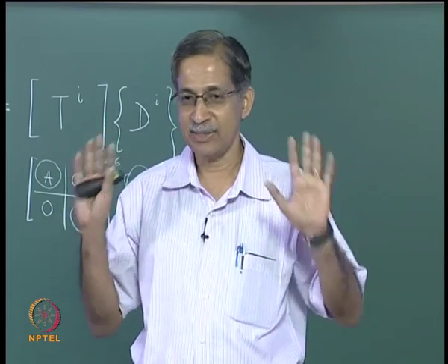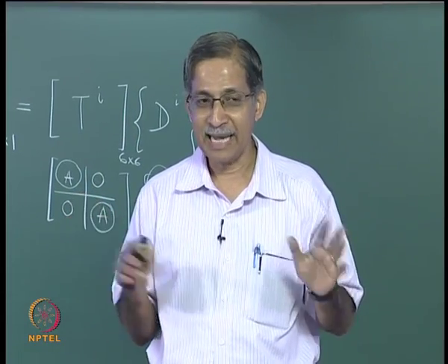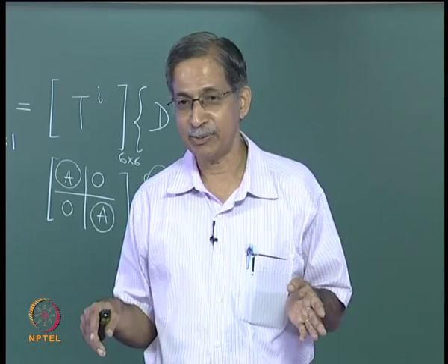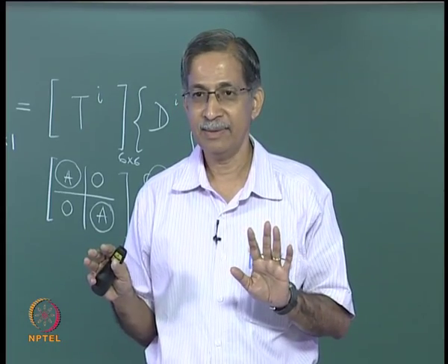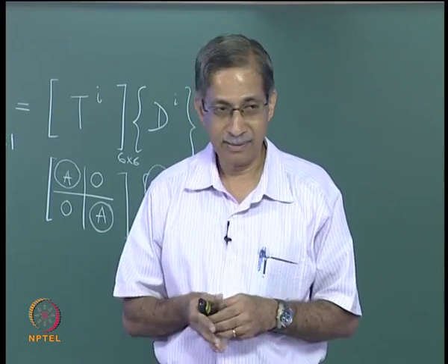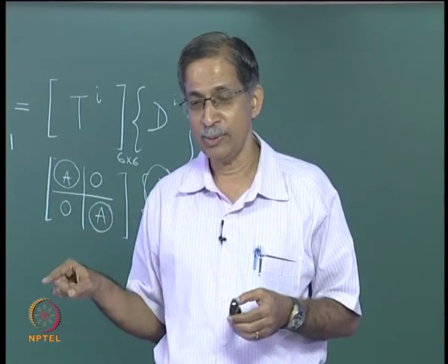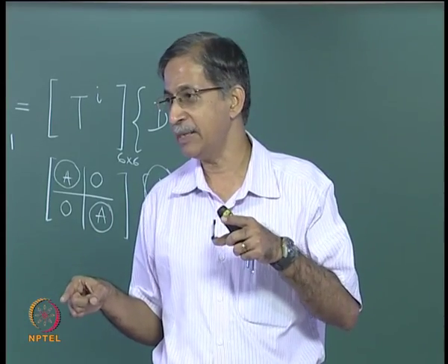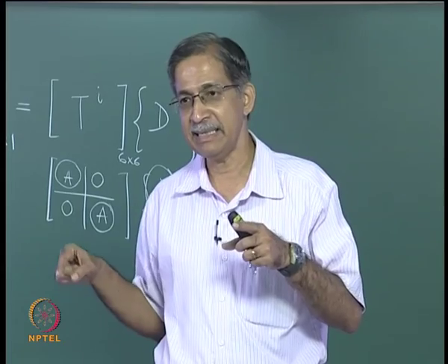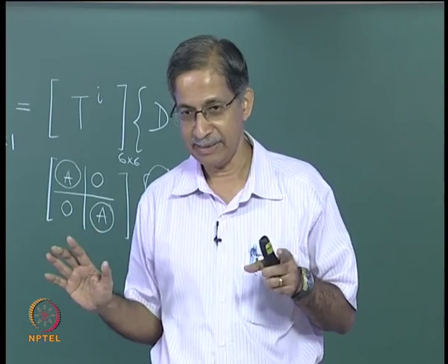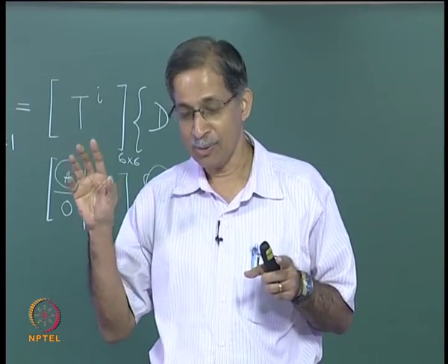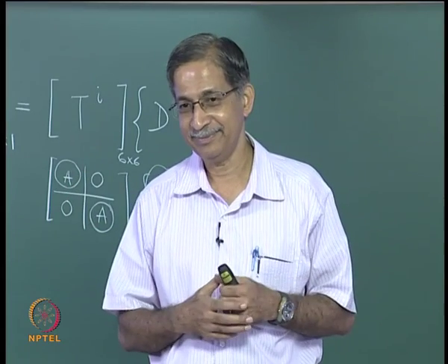First we began with a structure. In that particular frame, how many displacements did we have? We had 12, dA and dR, right? We had d1, d2, d3 all the way to d8, they were active degrees of freedom, and d9, d10, d11, d12 were restrained degrees of freedom. How are those linked with these?